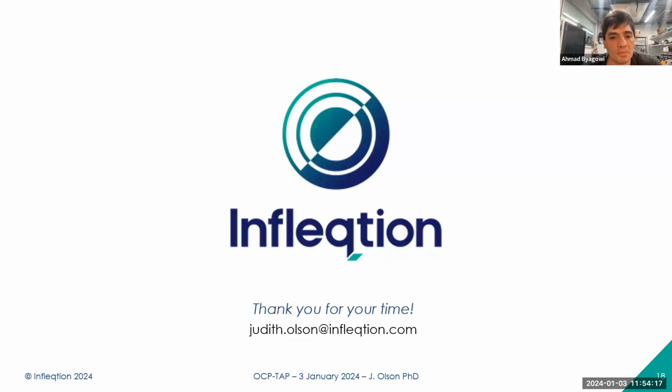One more thing I want to mention, which we were discussing with Paul last week, is the synchronization that we do today, like with PTP and so on. Synchronization is a little bit misleading. I would say the term is more tracking. You're tracking one clock to the other one with a numeric method. You just do some measurements. Nothing is perfect, and you go through making one clock track the other one.